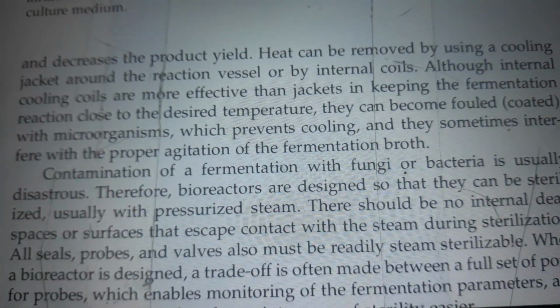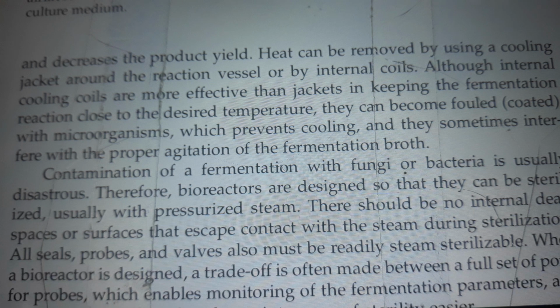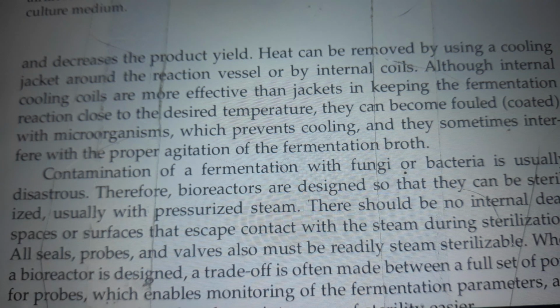Heat can be removed by using a coolant jacket around the reaction vessel or by internal coils. Although internal coils are more effective than jackets in keeping the fermentation reaction close to the desired temperature, they can become coated with microorganisms, which prevents cooling, and they sometimes interfere with the proper agitation of the fermentation broth.